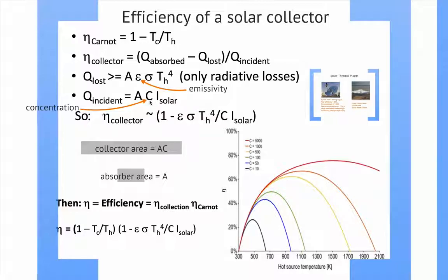So you might have a big collector, like a big Fresnel lens, let's say, on top of the collector, which increases your input aperture. Remember the very first lecture I mentioned the input aperture is important. This is how it becomes important. Here the area is multiplied by the geometric concentration factor. We'll see this again and again, so we'll look at specific examples. For now, just be aware of where this goes into play. This goes into play in the denominator.